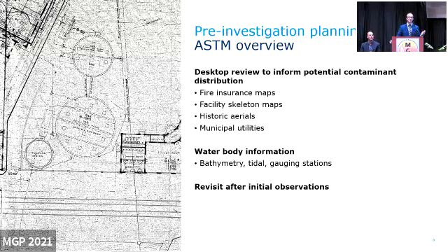So knowing where that slough may have been located is helpful for designing your sediment investigation, and reviewing historic aerials and those changes over time can be pretty helpful in identifying those sorts of features. Lastly, municipal sewer records are really helpful to understand different contributions from the sanitary sewer system to your site. You'd want to structure your investigation to understand the influences of those impacts relative to the MGP, to determine what may be MGP related and what may be contributed by others.